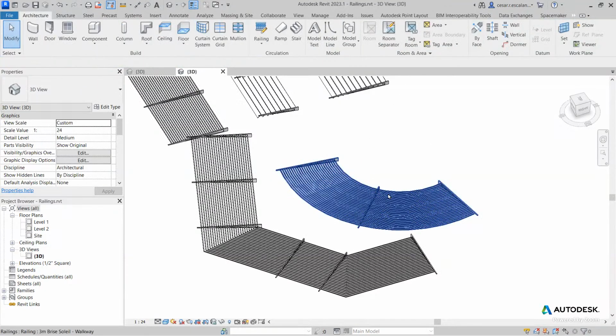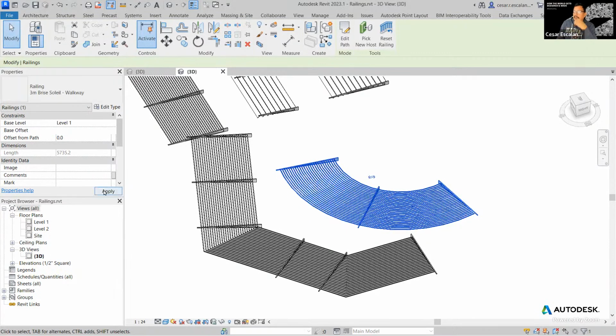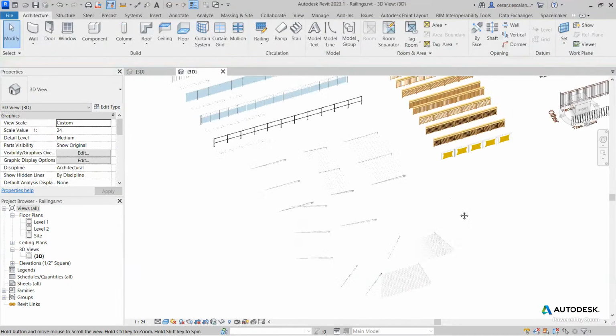It's just a standalone, right? It's a standalone. It might be hosted to a little piece of floor that represents maybe a beam, or it could be hosted at a floor with a base offset. This is hosted by level 1. If I know the bottom is 9 feet, just raise it by that distance. Yeah, it's pretty neat.